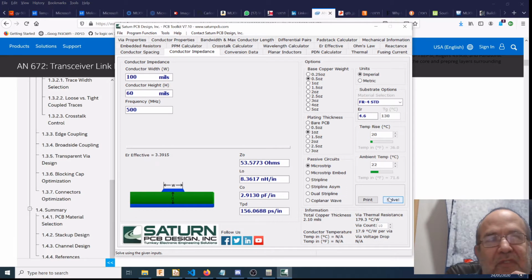And 2.5 millimeters, there's no way that you can do this on a 2-layer board, especially not with surface mount. There's no way of getting a 100 mil trace connected to a surface mount package. Not any that I know.